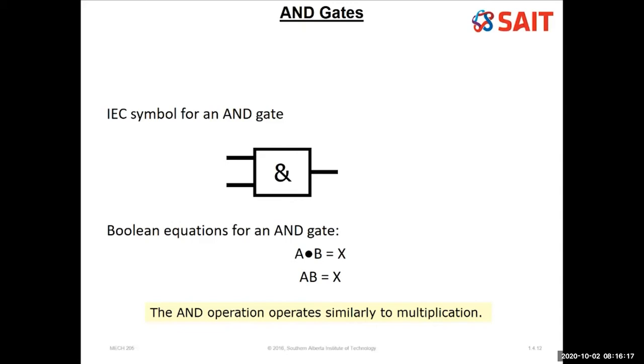It gets a little confusing because when you were at school, you learned 2 and 2 equals 4, or 3 and 5 equals 8. You learned it as an addition. You often use the word AND when we're adding, whereas really it's like a multiplication. If I think about those inputs, if I multiply them together, say I've got 3 inputs, input 1, 2, and 3, and say they are 1, 1, 0. I go 1 times 1 times 0 equals output of 0. So it works very much like a multiplication, and that's why we use this dot as a multiplication form.